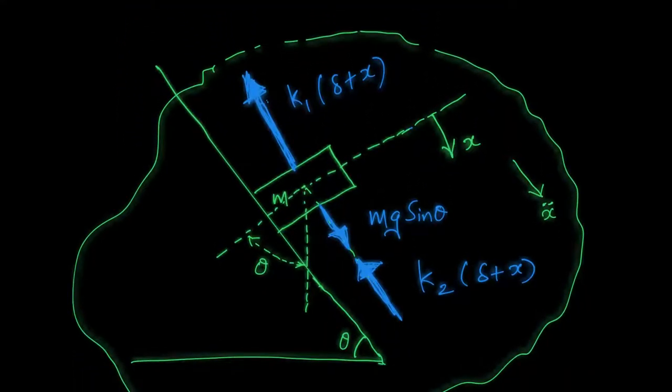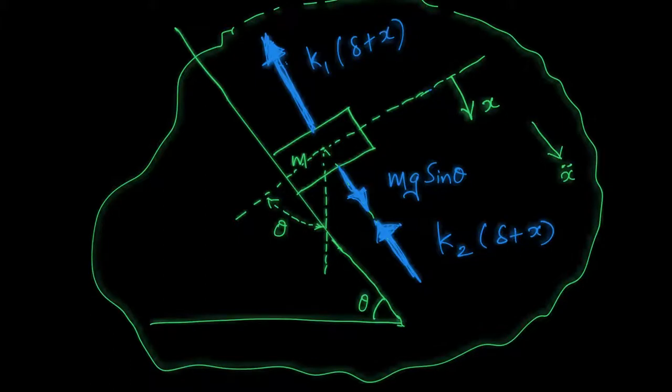That's how you arrive at the governing equation of a discrete mechanical system. So again, I'm drawing the free body diagram over here. Now this mass is accelerating with an acceleration of x double dot because it is vibrating. In the earlier case it was static deflection. Here it is vibrating, and if I put all the forces acting on this mass little m, the first spring will pull it up, but with a different force.